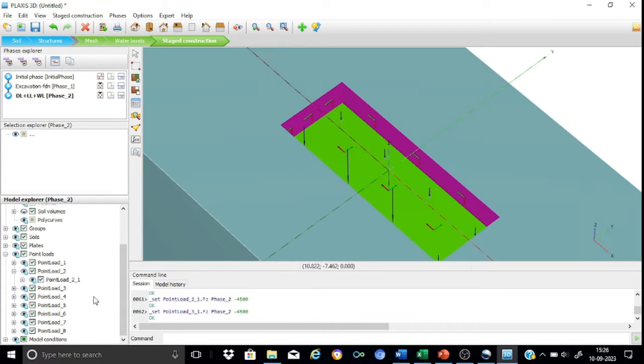So we can say that obviously represents point 4. Go to point 4. You can see that yes, this is deactivated. It's the right location. So here we know that the load will be minus 2500. So apply my F set as minus 2500 Newton.